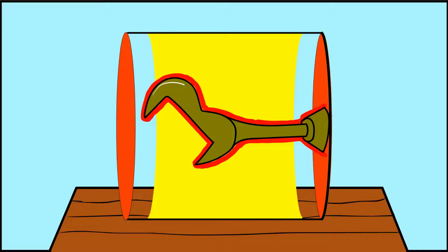In case of an improper burnout, the carbon from the wax pattern might still remain in the mold cavity, and this carbon, upon heating, reacts with calcium sulfate to again release the sulfur dioxide gas, and the sulfur dioxide gas results in the discoloration of the casting.